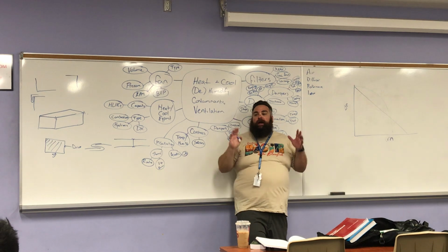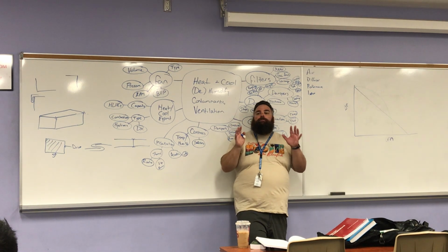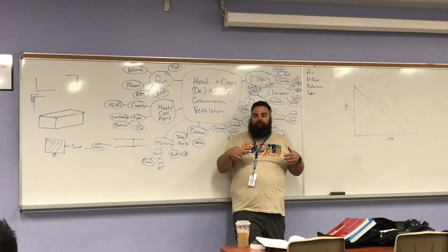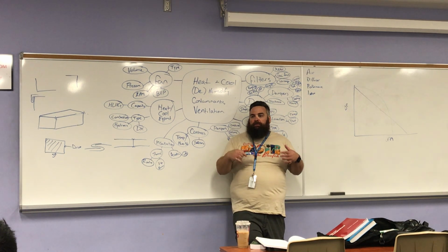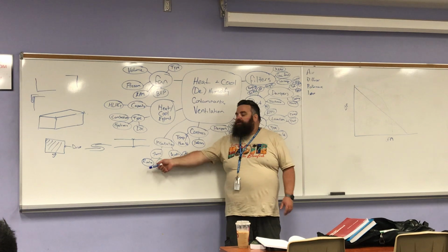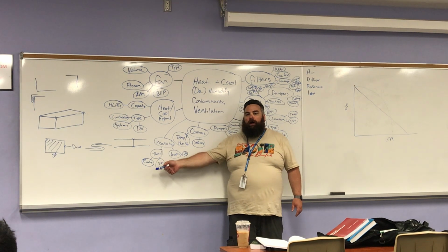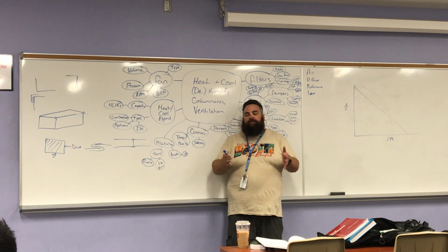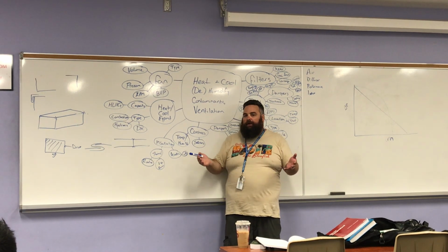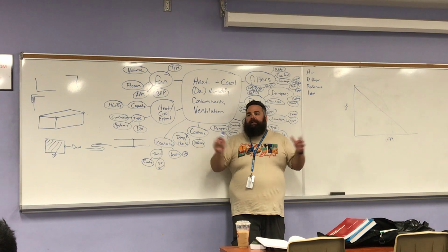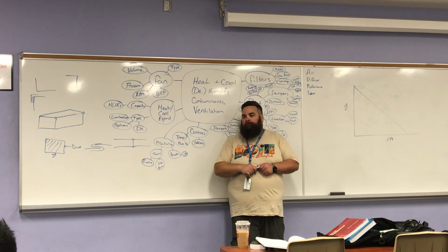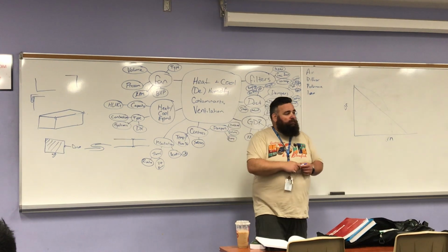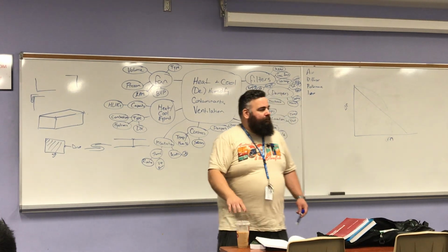So think about if I have cold air going through my duct in a warm, humid space. I have the insulation on the outside, I have my R value, but I also need my vapor barrier, otherwise I'm going to get condensation on the outside. If we put the acoustic insulation instead and treat that as our thermal insulation, we're still going to get condensation on the outside of the duct. That'll damage architecture, that'll cause corrosion. The acoustic insulation is the insulation that's inside the duct.